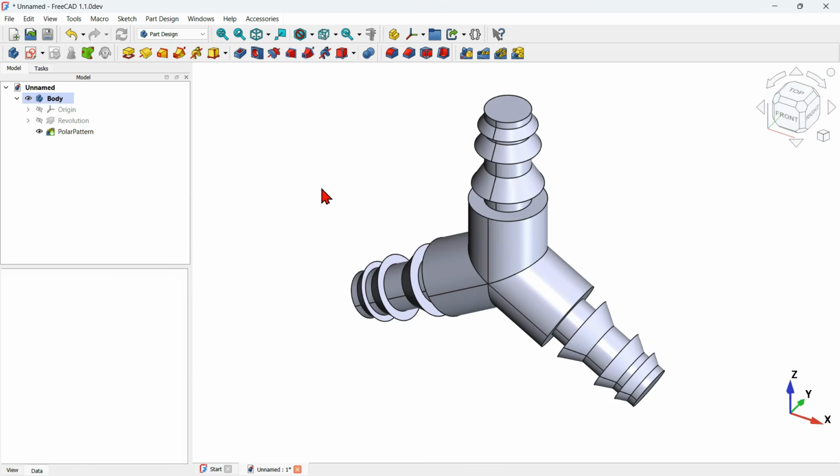And the next thing that I'll do is to create a hole on this part here. And to do that, I'll be using a subtractive cylinder. It's a primitive shape, and I will use it to remove material on this part here. So first of all, I will add transparency to this part here. So this way you will see what happens inside this part here.